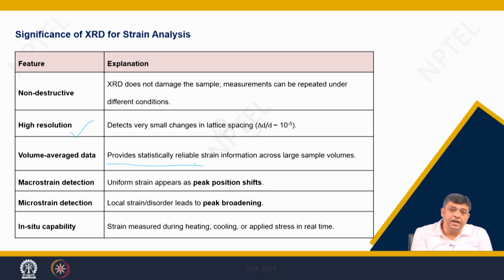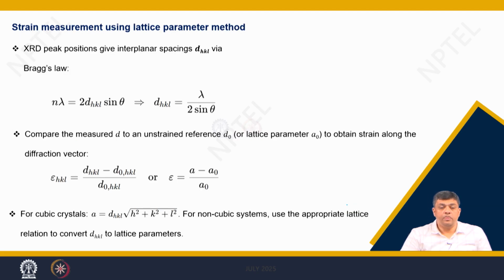You can apply stress in real time and then collect the X-ray diffraction data, analyze it, get the alpha, beta, gamma, ABC parameters, and you can find out the magnitude of strain which is getting stabilized. So, it is a very simple but a powerful technique to carry out the strain analysis.